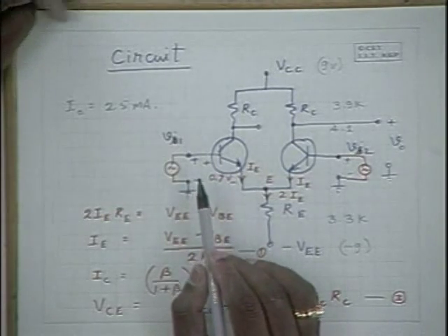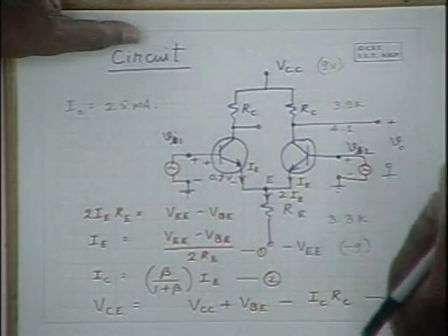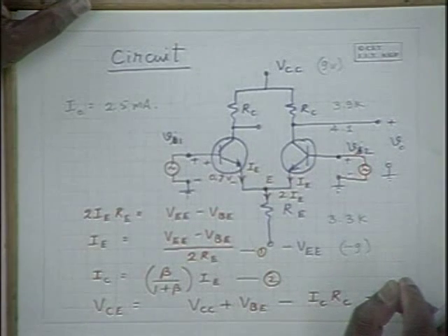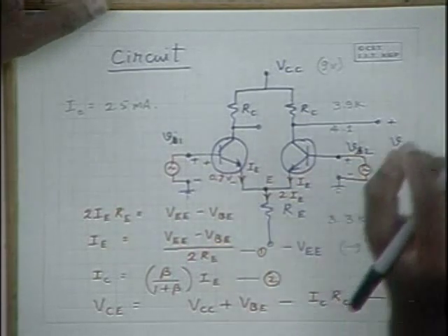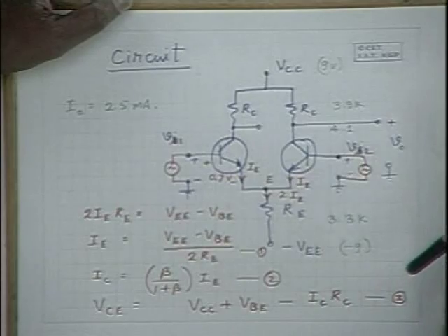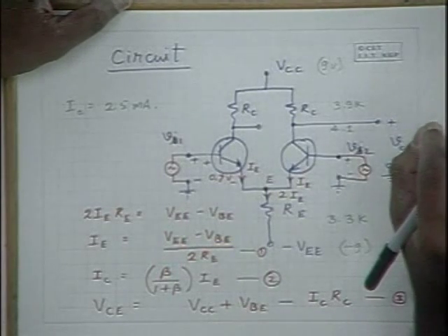Please note that in the common emitter amplifier which you have seen, we were using coupling capacitors to isolate the DC value at the base of the transistor from the input signal. The input signal, if it's an alternating signal, is usually a zero mean signal, meaning part of the cycle goes above 0 and part of it goes below 0, and the average is 0.